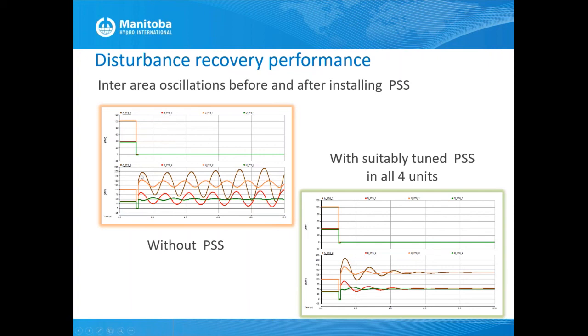I'm sure you have seen such situations. Very likely on the first swing or second swing, it might go. But a gradual increase in the magnitude of the angle means you have insufficient damping torque. I think I adequately answered that, but if you have questions, we can discuss that later.